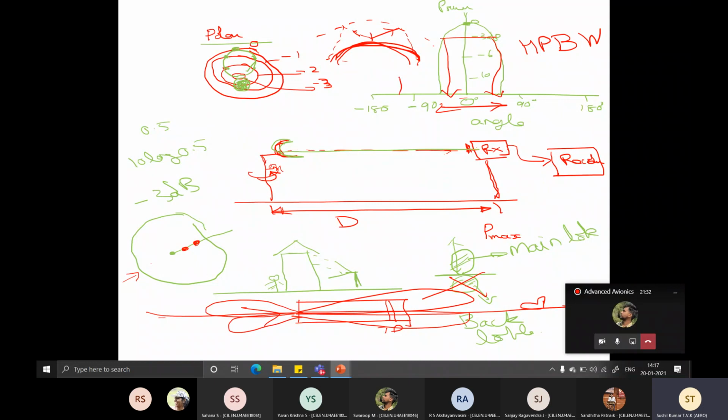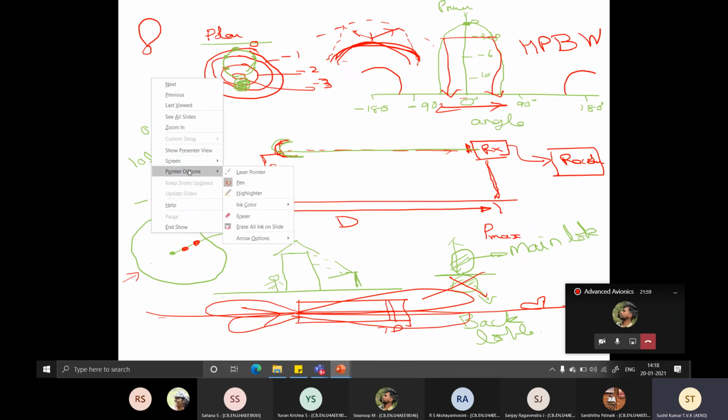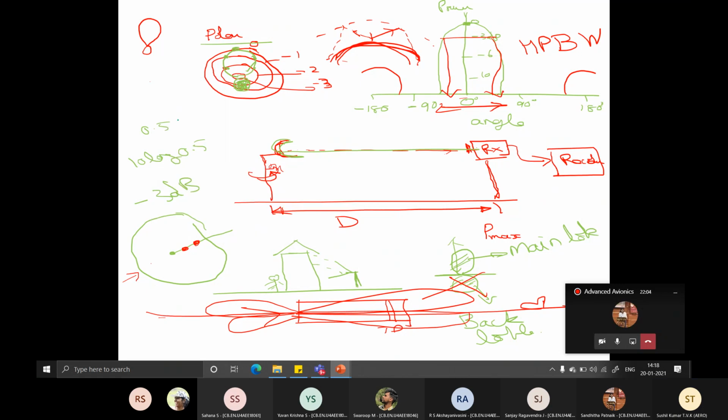Similarly, because of back lobes, you will be having something like this also. In addition to back lobes and front lobes, something very undesirable happens. That is called the side lobes. At least back lobes, you know it's 180 degrees out. Side lobes are something like this. Suppose this is the main beam and you have a back lobe. Side lobes will occur in different orientations. So you will have unnecessary lobes like this. And this is what is used for electronic jamming. If you know the radiation pattern of the radar, what you do is you turn on your jammer not when the main lobe is pointing at you, but when the side lobes are pointing at you. So effectively, you can actually sneak into the radar using the side lobe jamming.